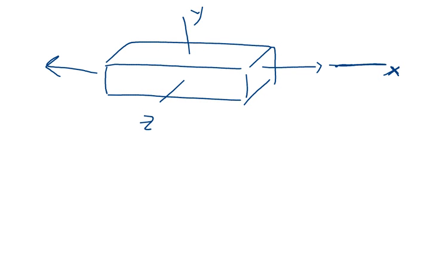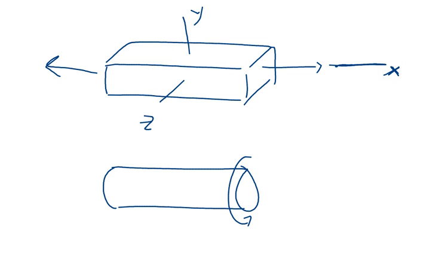Right. Same thing when you have a shaft that's in torsion. If I have this shaft that's in torsion, it makes sense to line up my x-axis with the long axis of this rod again. And then the other two axes are going to be y and z. If I define my axes like this, for these two cases, then yes, in terms of x, y, and z, I do get purely normal stresses and strains in the first case, and I get purely shear stresses and strains in the second case.